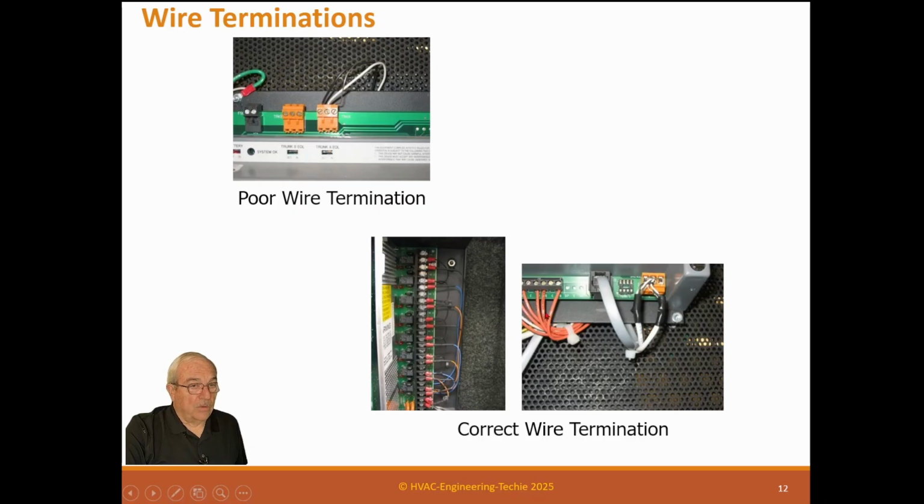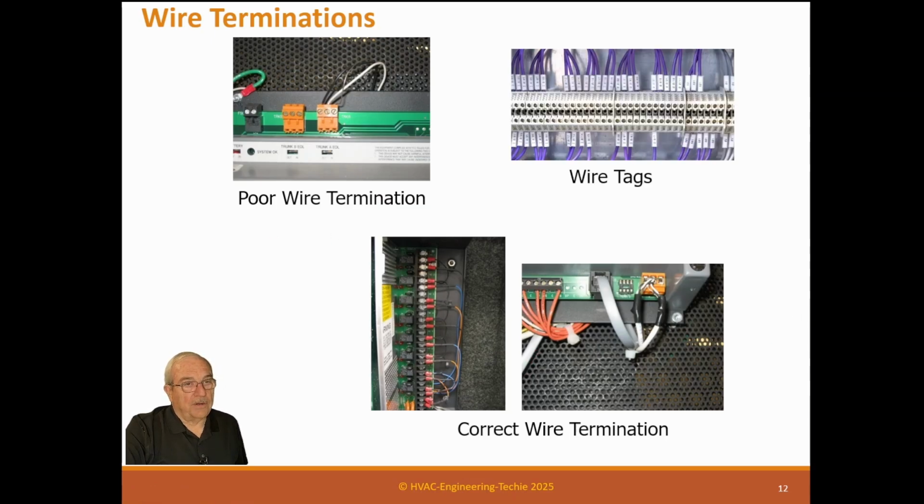These are I/O wirings, and these happen to be digital outputs, and these are THN wire. And you can't see them here, but these are a bunch of conductors, sensor wire with a twisted pair with a shield. And then these are wiring tags. This happens to be an industrial panel, but you'll see that they have all these connectors, and they have all these numbered wire tags telling where these wires go.